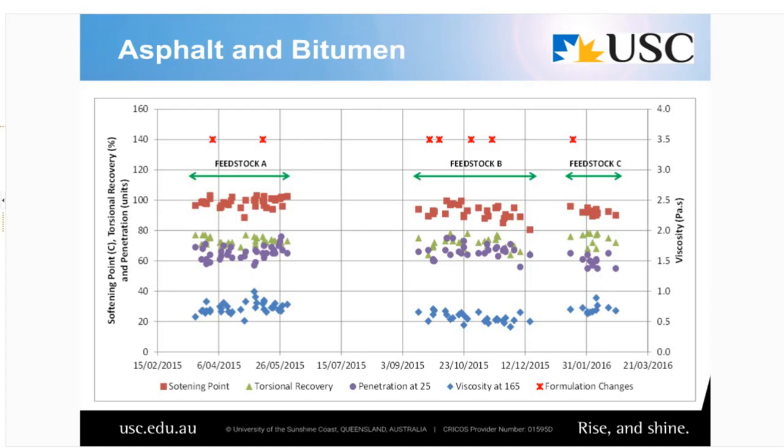You might add $400 a tonne for the polymers that would typically go into that bitumen to produce what we would now call an airport-suitable PMB for runway resurfacing. So it adds significantly. That's for the bitumen cost.